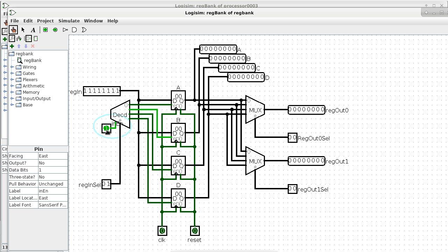So what else do I need to do in order to update register B? The clock, right? We need a rising edge at the clock. So now we say, okay, clock line goes from 0 to 1, which makes a rising edge, and now register B is changed.